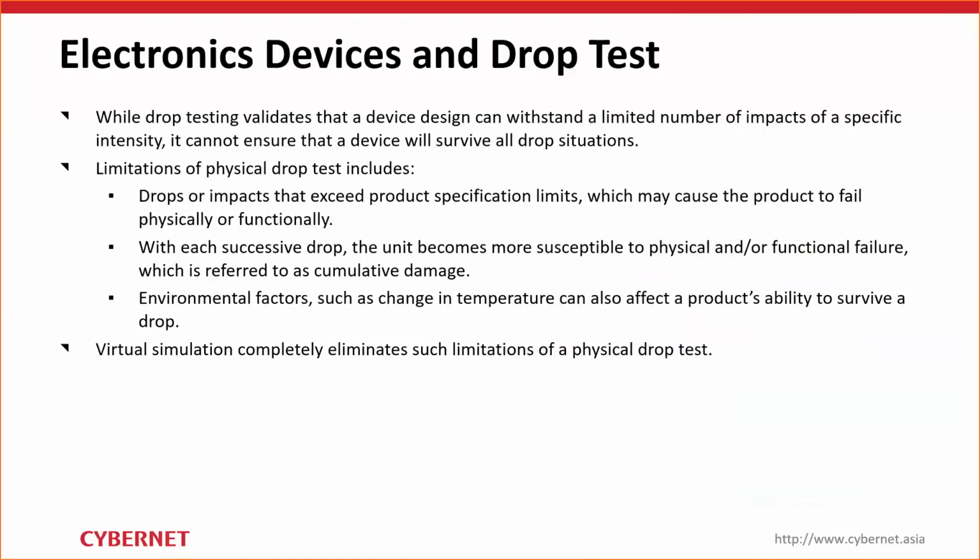Several limitations of physical drop testing include drops that exceed the product specification limits, which may cause the product to fail physically or functionally. Another limitation is the cumulative damage from each successive drop. And another challenge is environmental factors such as fluctuating temperature.